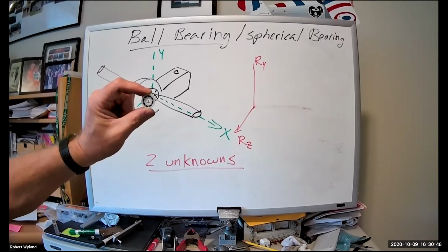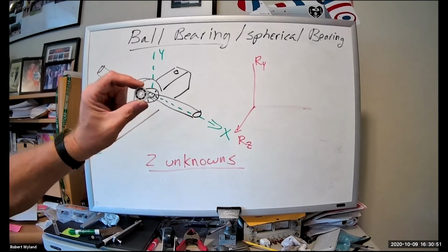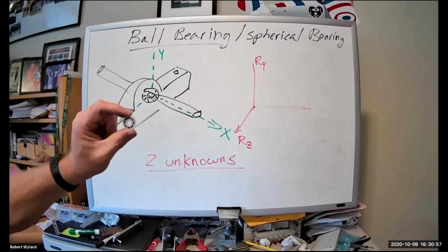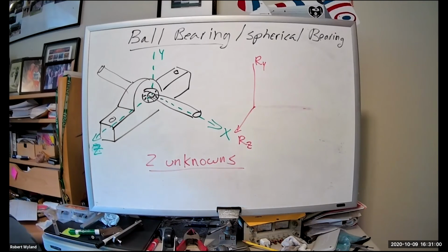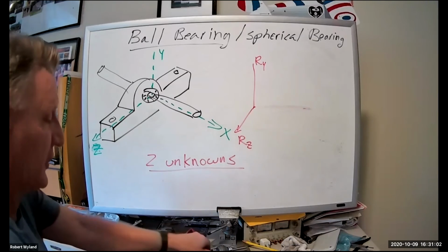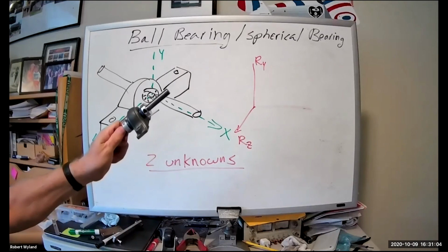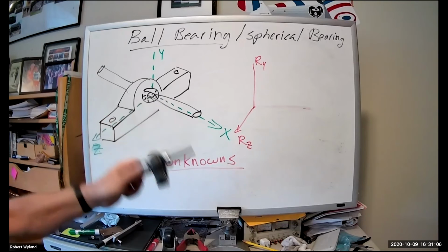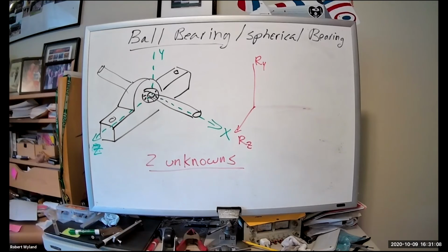So if we had a ball bearing like the one that you showed us, the first example, the skateboard one, would we treat that as the thrust bearing from the last example? You would treat this as a plain bearing or a journal bearing. Okay, a journal bearing. Got it. Yeah, unless there were some sort of thrust plates mounted, like on the other one I've mounted the thrust plates on. So I mounted these thrust plates on there. Okay, thank you.